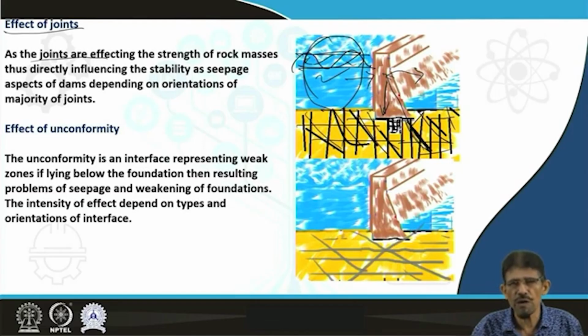Friends, you know liquid state and solid state. So ice has an expansion in volume, which is going to create a lot of problems nearby the top portion. Beside this, we also have silt pressure and others. So all the pressures are countered by the weight of the dam, and if this weight of the dam is affected by other forces like upthrust and others, then there is a problem.